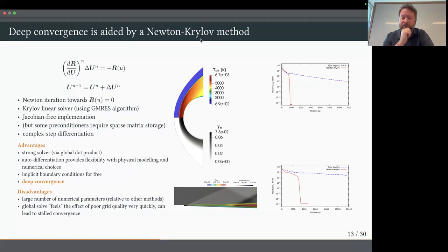When we use limiters on unstructured grids, they are decoupled in the code, and we're able to freeze them at some point in the convergence, and that allows us to get deep convergence. We don't have that for our structured grid technology just because of the way the reconstruction and limiter are all built and rolled into one. It could be done separately, but we just haven't.